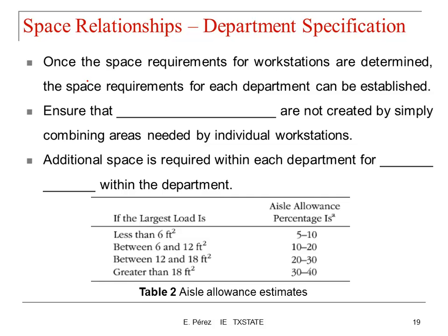So once the space requirements for the workstations are determined, the space requirements for each department can be established. So you need to make sure that the operational interference is not created by simply combining the individual stations that you're going to need for that department.